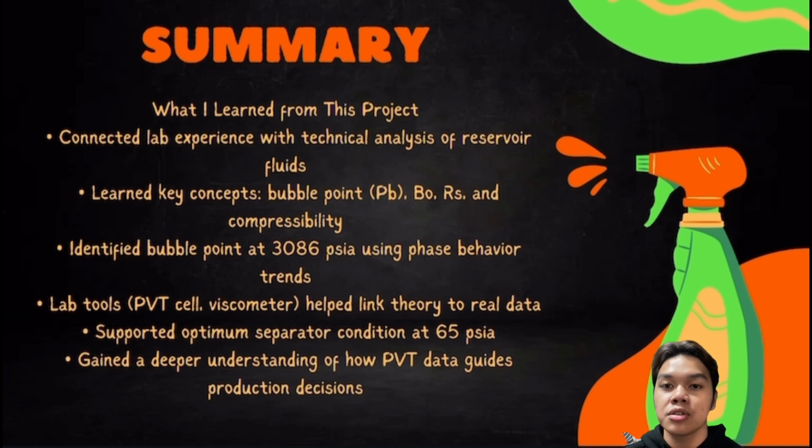The lab's focus on compressibility and phase envelopes also helped me analyze pressure-volume relationships more accurately. The equipment that I saw, like the PVT cell and viscometer, gave context to the experimental data we used and supported our determination of optimum separator conditions at 65 psi. So overall, to conclude, the lab visit has deepened my understanding of fluid behavior and its impact on reservoir performance, which directly enhanced the quality of our analysis.